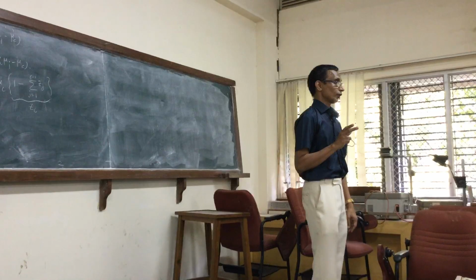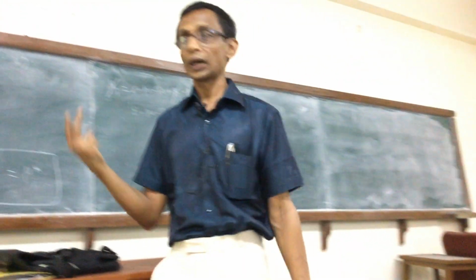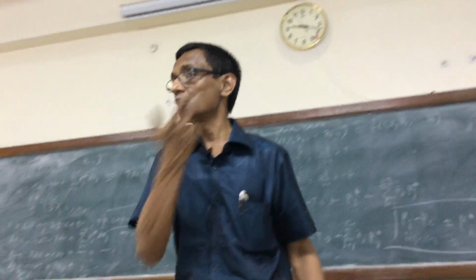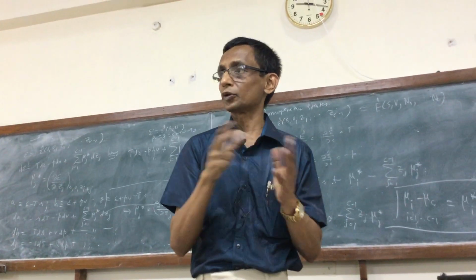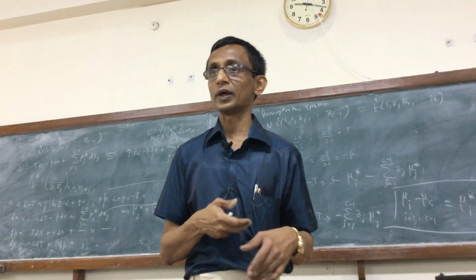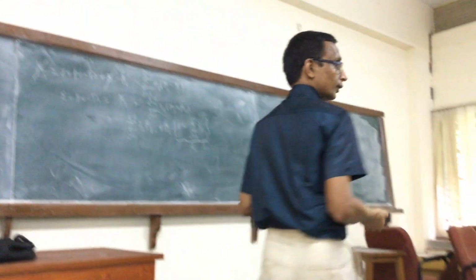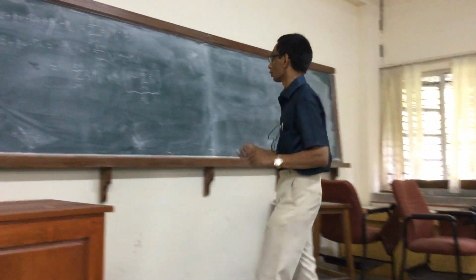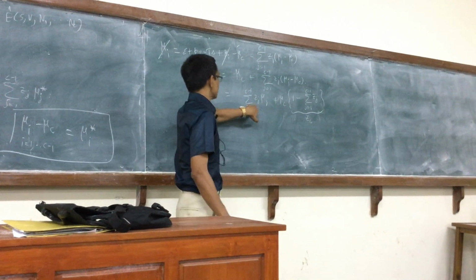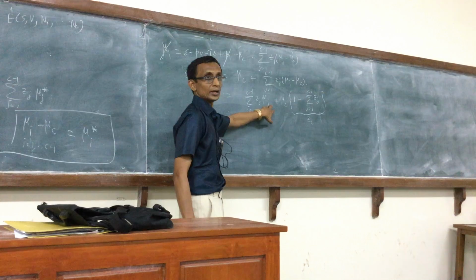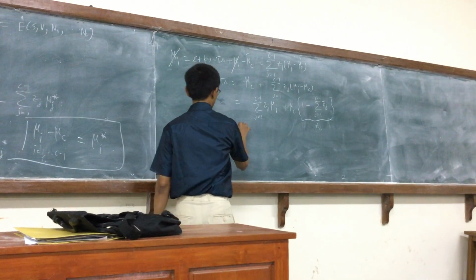Be careful about what it is summed over. Sometimes it's convenient, as we will now see, even when using mole fractions, to introduce the ZC into the expression to make it compact. And even though we know that ZC is not independent of the other c minus 1 mole fractions, that's exactly what will happen. So this is ZC mu c, and this is the sum over j equal to 1 to c minus 1 of Zj mu j. So we get this very famous relation attributed to Gibbs.